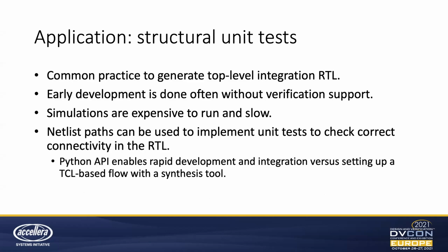So the second application where we've used this is structural unit tests. The motivation here is that it's common practice to generate top-level integration RTL, and early development of this RTL is often done without verification support. Whenever you're dealing with the top level of a design, it's a long process to bring the verification up, and once it's there, it's expensive and slow to run simulations. You don't want to be debugging basic issues in the design through the verification simulation test bench.